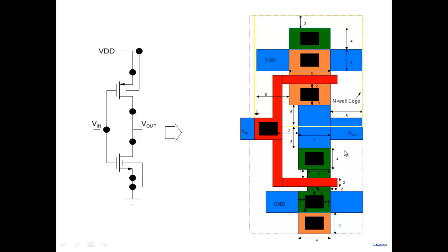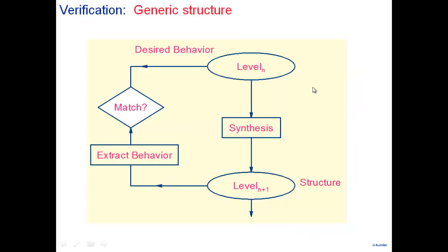the dimensions are obtained from the sizes of the transistors here. So this was taken as 3 lambda by 2 lambda, and this one was taken as 6 lambda by 2 lambda, lambda being for us 0.3. And the rest of the dimensions came from the various rules that were there. So let's look at this layout in a little bit more detail.